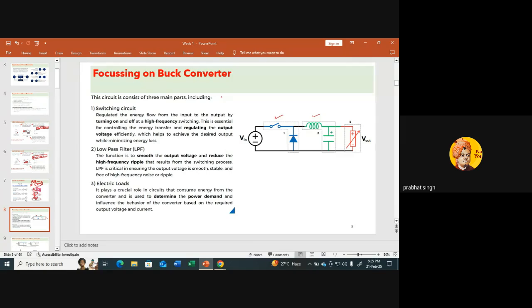It allows the signal below the level of bandwidth frequency. Yes. Basically, it allows the lower frequencies within the bandwidth if you're defining a band, and it reduces the higher order frequencies. So we know that if you have a high frequency output and we are neglecting the high frequencies, from Fourier analysis, if you see the FFT of any high frequency signal, there will be a DC plus the rest component. If you neglect the rest component, then we will get the DC of it, which is basically the average of it. In this way, the low pass filter works.